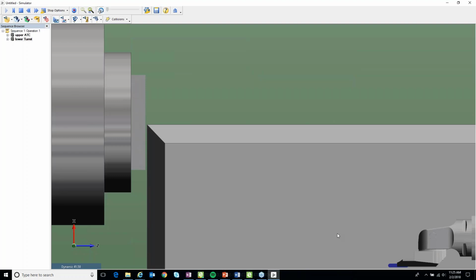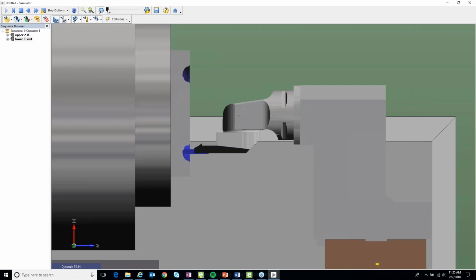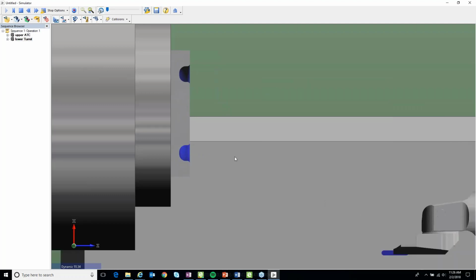We'll see how that tool comes in and very easily rolls in. We've asked the cut to maintain a single cut direction. The software quickly runs the shape and then the finish pass that we've asked for. This is a great application for perhaps your first experience with rough waveform turning. Customers often start with a full radius groove such as this.